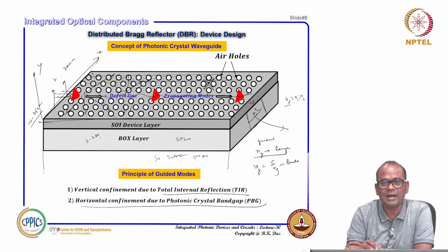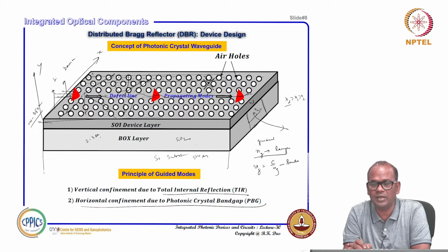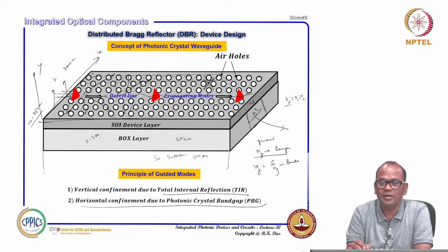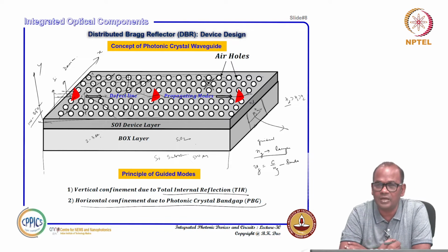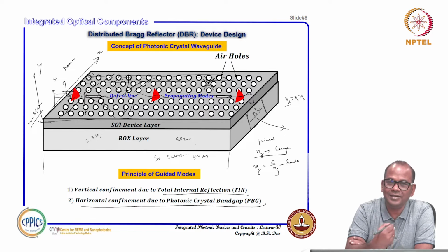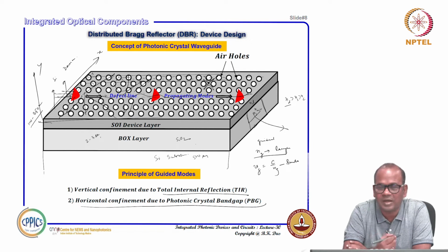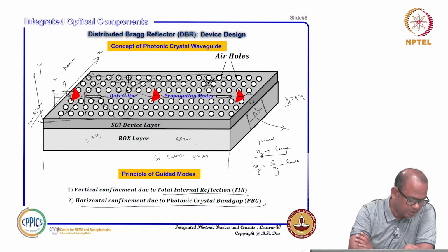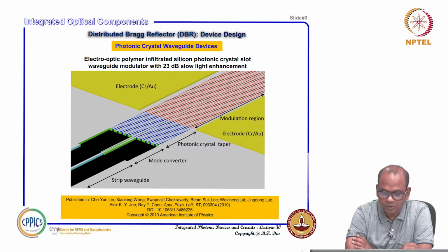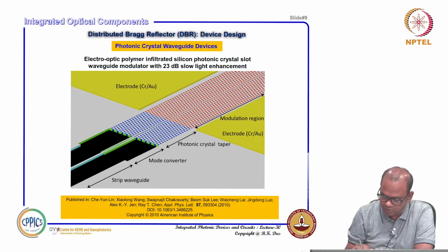So, when a guided light travels slowly along the photonic crystal waveguide, it will interact more, it will take more time to interact with the material. So, that interaction enhancement is helpful for certain device applications. I will show one example here. Recently, I think not recently, in 2010, demonstrated by Chi-Yun Lin et al.